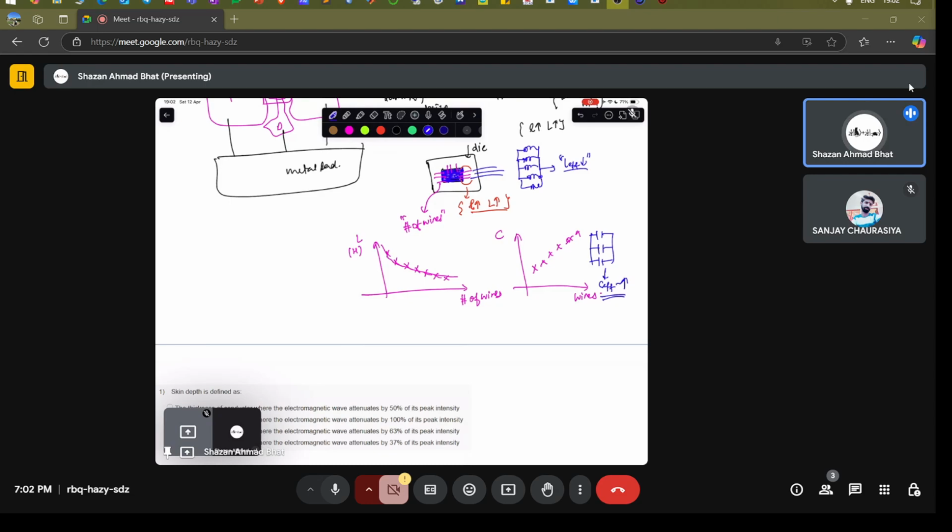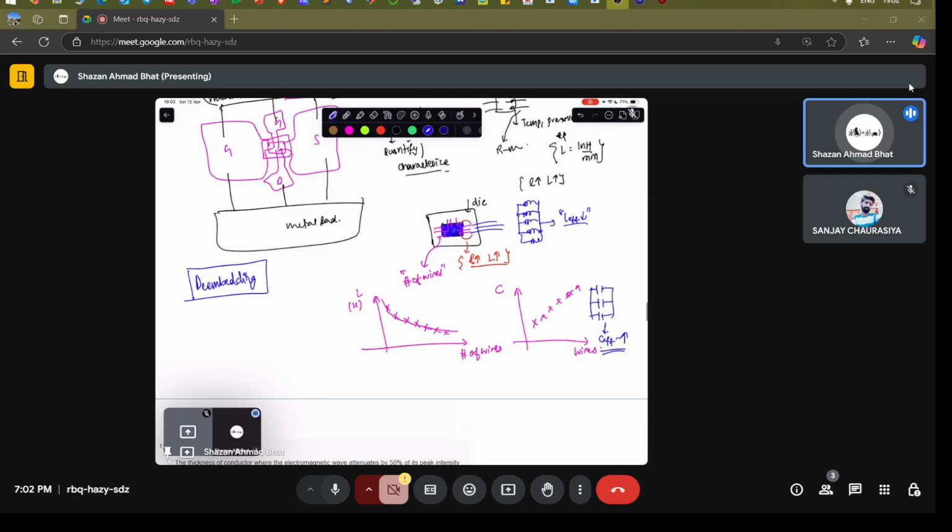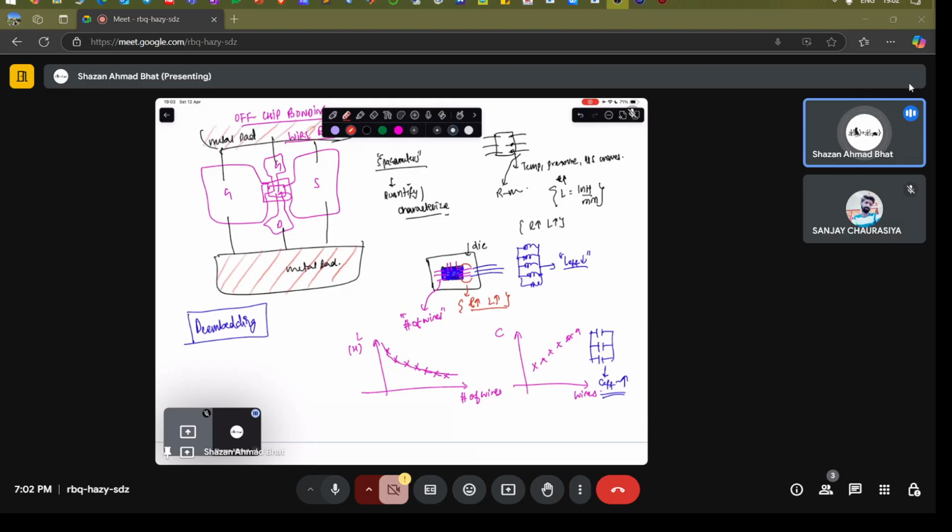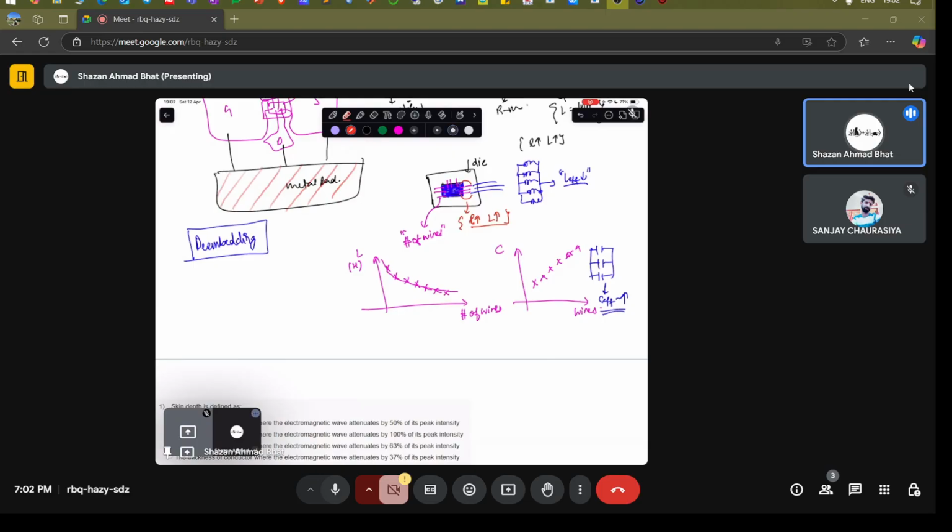Yes. Okay, there is something called de-embedding. De-embedding, just a fancy name. I don't know why they use these names. Like I talked about, you have a metallic pad here, which is basically used in order to extract the signal. So whatever the parasitic resistances, capacitances, and inductances are brought by these metallic pads or external peripherals into the system, when you subtract them from the original values of the capacitances, inductances, and resistances, that is something called de-embedding.